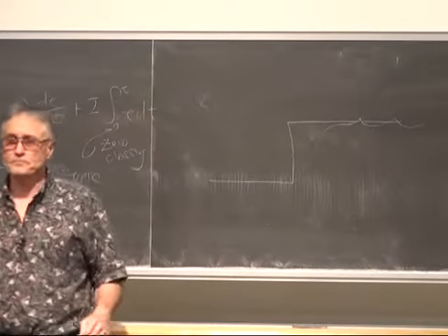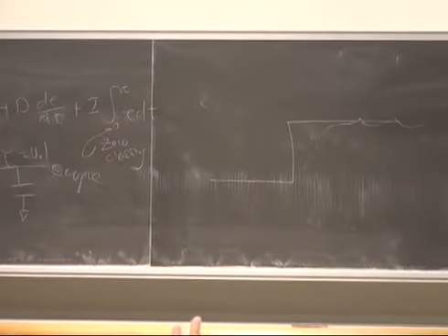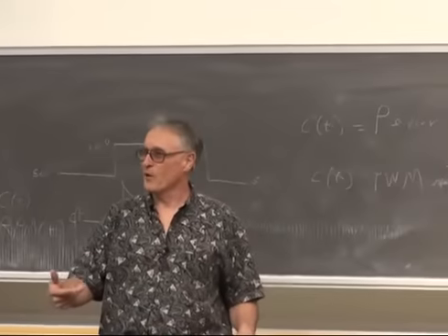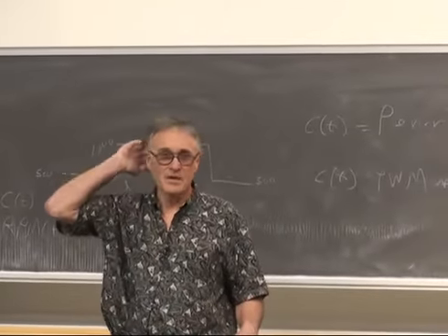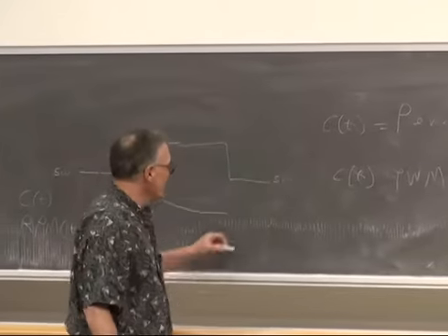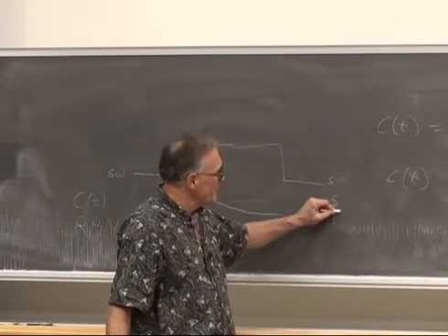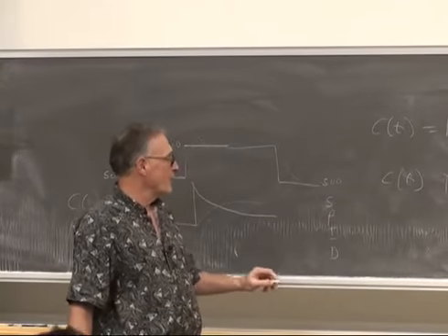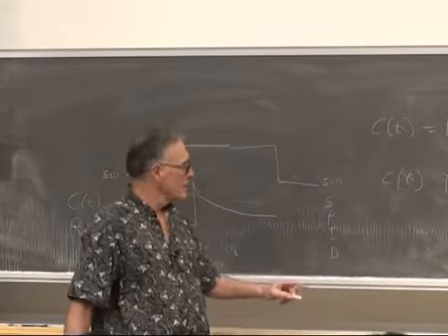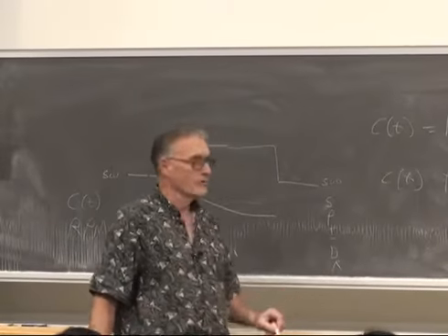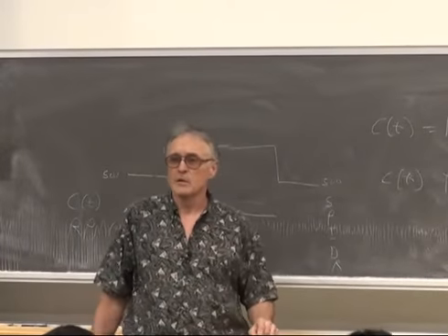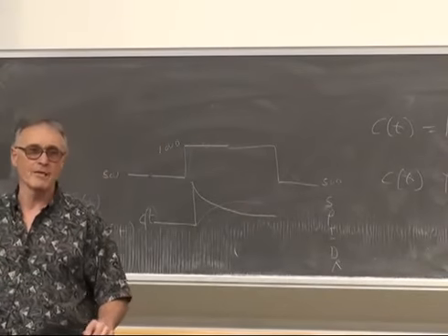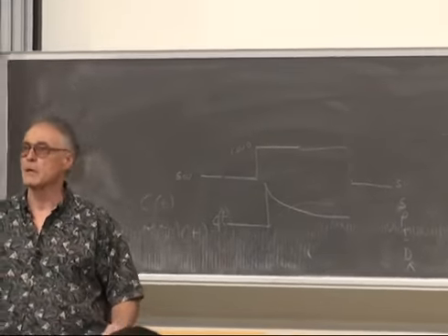Try it and see. So you could have another parameter that you throw into the control system. I think I said that you need to be able to interactively set the speed, the proportional, the integral, and the differential term. Maybe you ought to have another parameter that you can enter, the reset value for the integral in fractional terms, so that you can interactively tune it without having to recompile all the time.